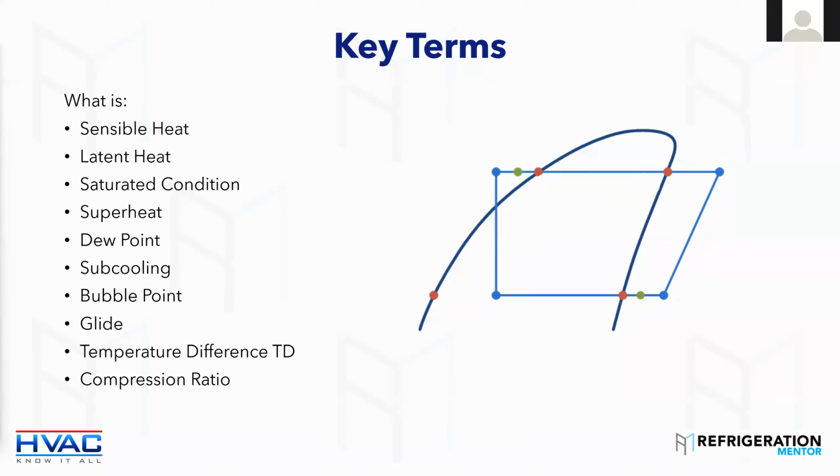Well, it's not moving any refrigerant. Well, you got it. You said it. It's not pumping anything. Usually, like for me, I've worked on a lot of recips, and the valves can go bad on a recip. You can blow a valve up if you get a slug of liquid or whatever. And if the valve goes, basically you're not going to pump refrigerant. You're going to equalize the pressures across the high and low side. The pistons are still going to move up and down, but you're not going to pump any refrigerant.